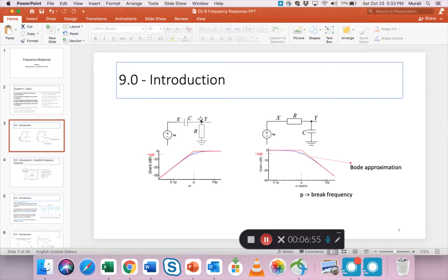Not really gain, it's more of a voltage division. But anyway, this side, the y-axis is always called gain, and it shows in dB. You probably also remember the minus 3 dB point, right? On this blue graph, which is the actual value of how the output voltage by input voltage, the ratio drops with respect to frequency. At 0 hertz or 0 frequency, this is an open circuit, right? So no voltage appears at the output, that's why you see 0.